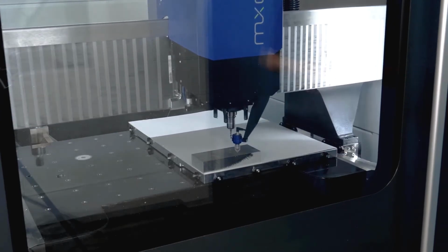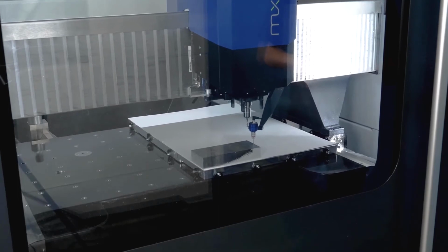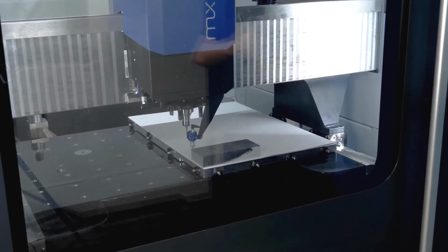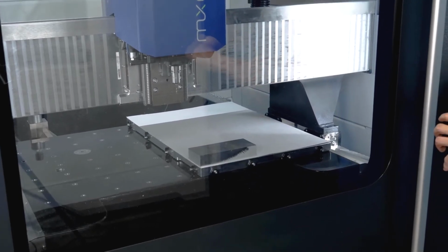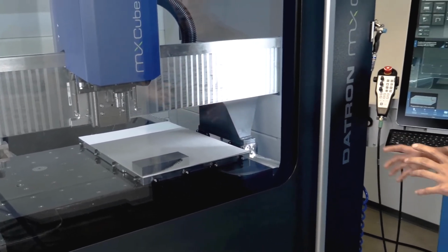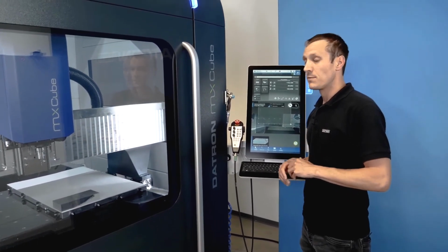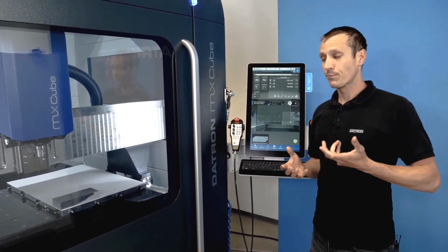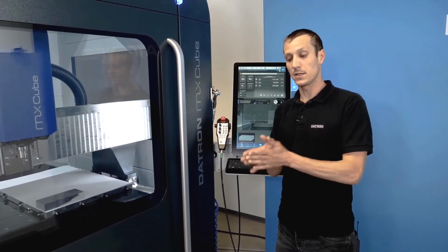So it would now set the origin in the center of this part, and because it had two points on the back end of the part, it would also make a perfect alignment in terms of the rotation around the Z-axis. So this is an extremely nice feature when it comes to parts that need a second operation.